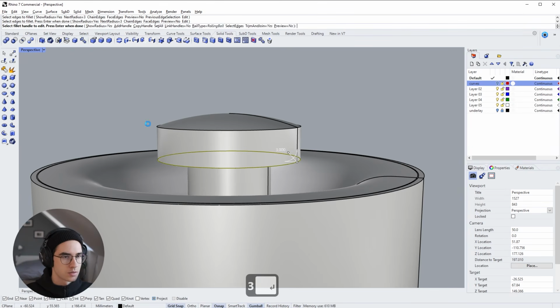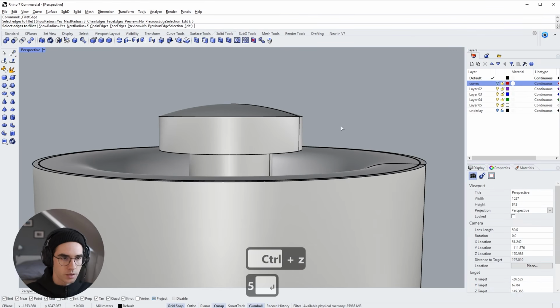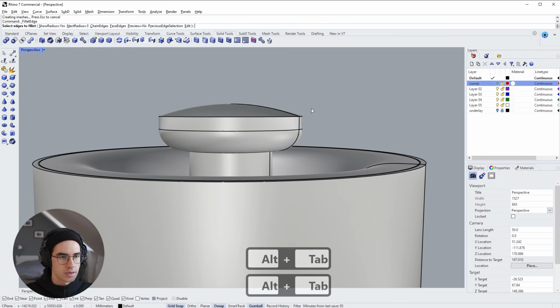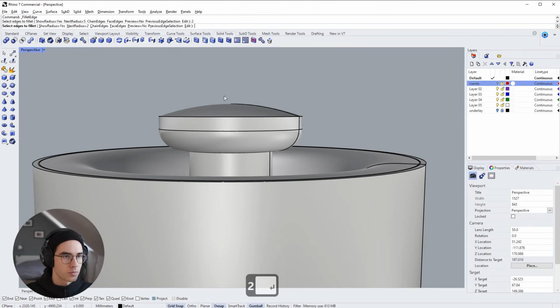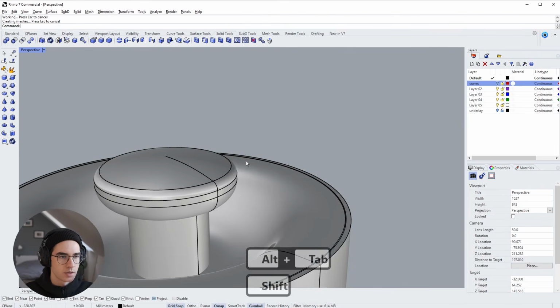Let's see how this works out. Yeah, we can go even higher with 5, go back and hit it again, 5 millimeters, since this is quite soft. So right click again to select edge fillets again, and the top one should be maybe 2 millimeters. This creates these soft edges of the handle.